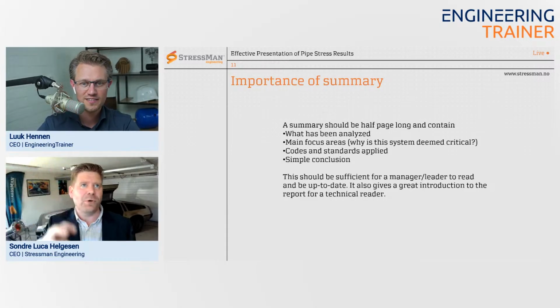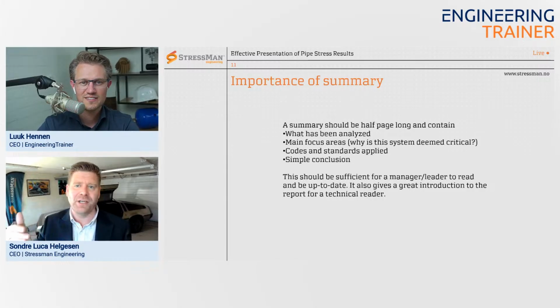If you can see the support types, you can get pretty much data from doing that. Even though if it's not spot on to the millimeter, that's no problem when you're doing the analysis. That will be a bigger problem when you're doing design, for example. It has to fit in the end. But from the purpose of doing a recalculation, if it's off by 10, 20 millimeters, well, that will not make a change there.